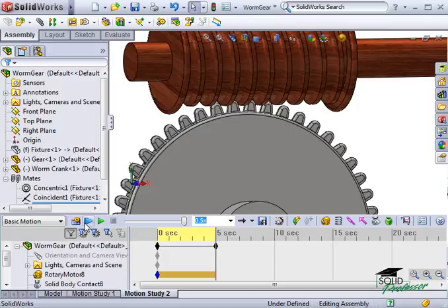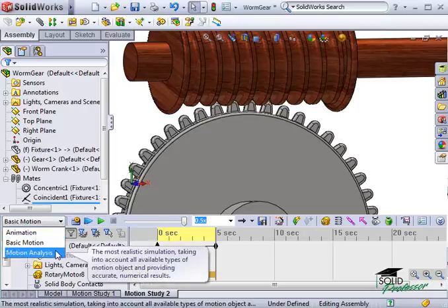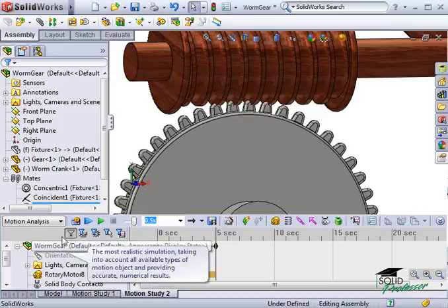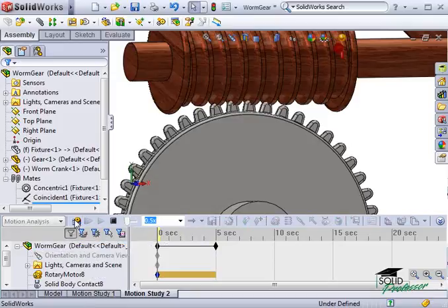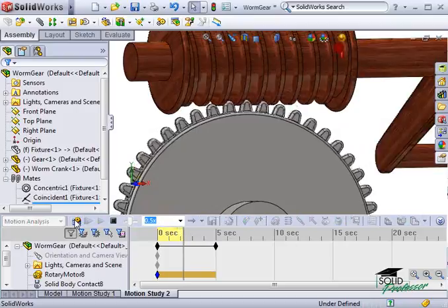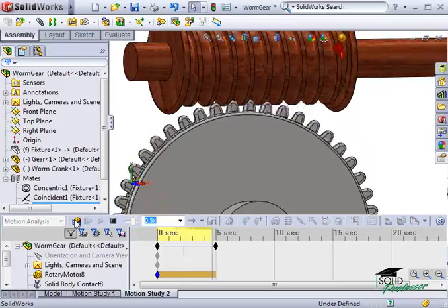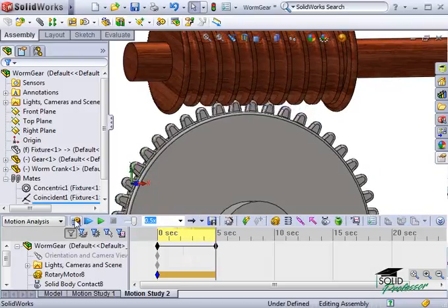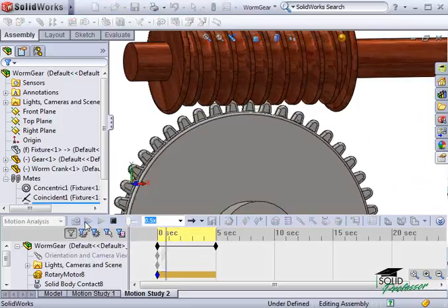Why, you might ask? The answer is speed, so SOLIDWORKS can crunch the calculation quickly while keeping the tool relatively simple to use. In the full motion simulation package, on the other hand, you have full control over the penetration condition, so the animation can run smoothly. I'll switch this to a motion analysis study, and then recalculate it. The default penetration setting in full motion is set much lower, which also results in a longer processing time. But when the study's finished calculating, the motion's quite smooth.